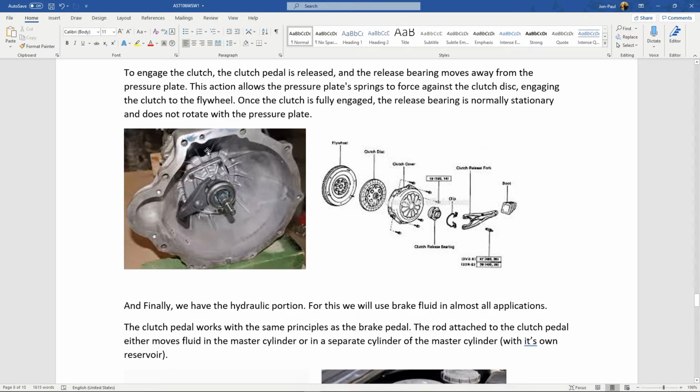So pretty please, if you swap the clutch, take a pressure washer or something and clean the inside of this bell housing out so that it's not full of old friction material. It would suck if that old friction material got on the new clutch and caused it to slip or something after you spent all day replacing this.